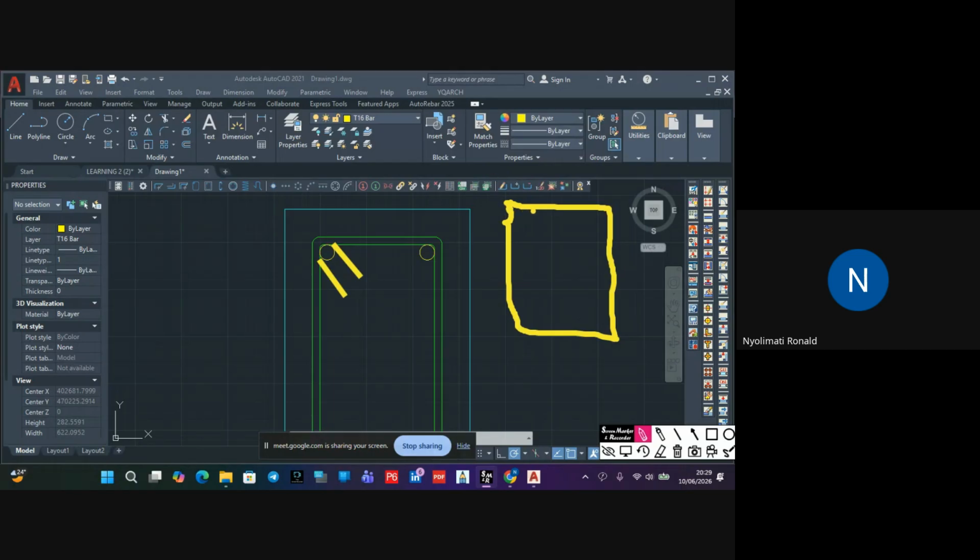So the reason you let this bar come like this and enter inside, and this one also comes and enters inside, is for proper anchorage. When this overlap comes like this, there's another bar running here, so they get tied on this bar for proper support.